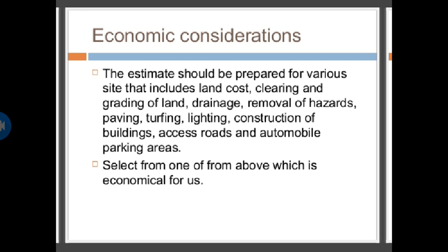Economic consideration. The estimate should be prepared for various sites that include land cost, clearing and grading of land, drainage, removal of hazards, paving, turfing, lighting, construction of buildings, access roads and automobile parking areas. Select the one from the above which is economical for us.